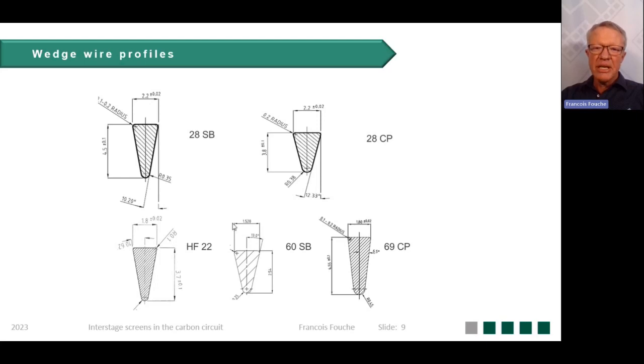We will also study the release angle. And I believe the sweet spot is between 10 and 13 degrees, and this is required to minimize pegging of the slotted apertures. There are also practical considerations, such as weldability. As we weld finer profiles, it becomes more difficult to weld, but we are able to weld profiles down to a head width of 1.5 millimeters.